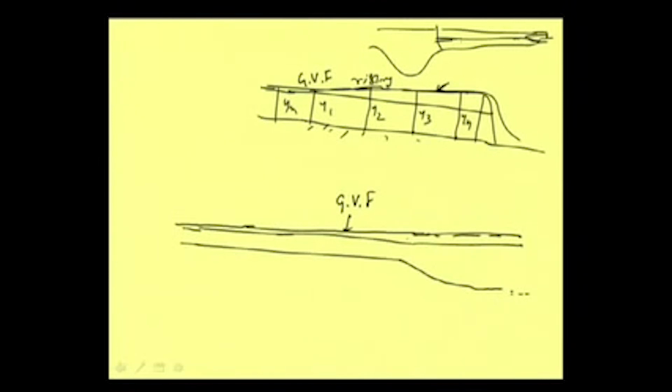And one point we should remember, though many a time we draw a gradually varied profile, suppose giving a barrier, we are giving this barrier and we are drawing a line like this. Apparently, we get this feeling that okay, depth here is less, depth here is more. Then a question may come into our mind, how is the water flowing from lower depth to higher depth, because here the depth is higher and the flow is moving in this direction. But of course, total energy at the upstream level is always more than the total energy at the downstream level, and that is why the water is flowing.